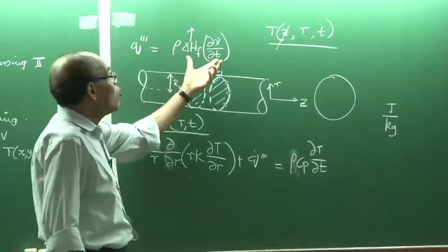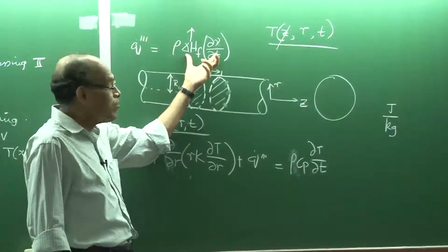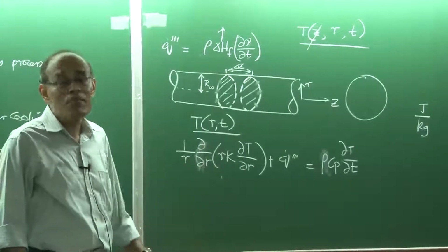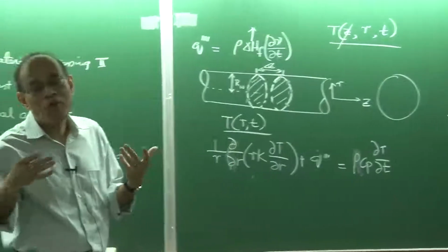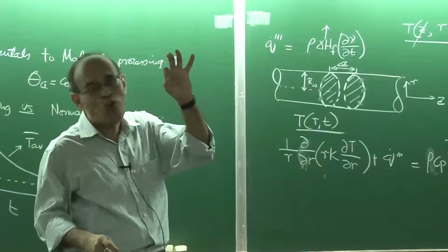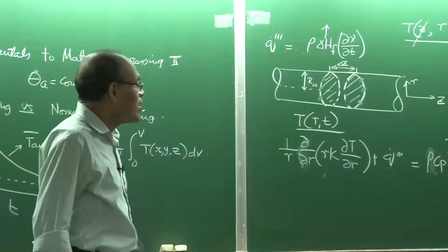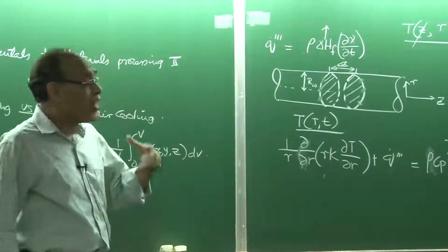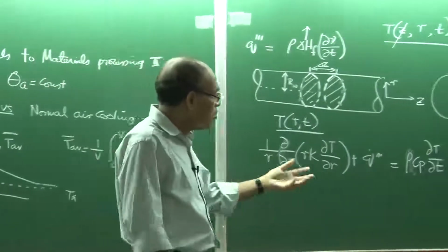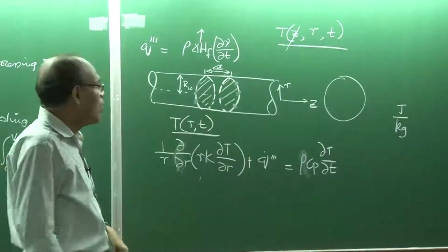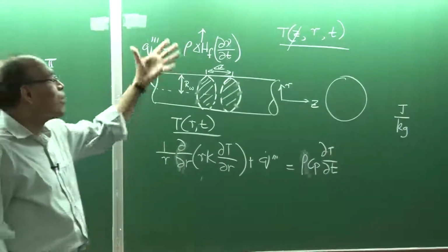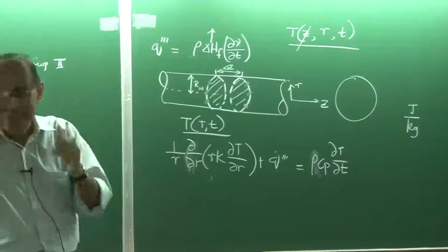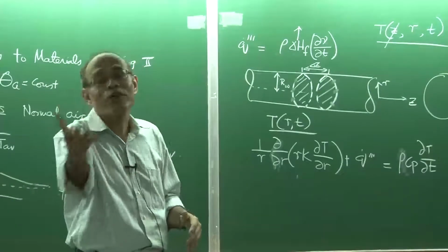Now the question is, how do you know how the phase change is taking place? For example, you can club with an iron carbon phase diagram, assuming that you are doing air cooling, and you know that the thickness is so small, nowhere will you get the critical cooling rate. So the time transformation diagram does not come into the picture. You can assume that the phase change is occurring close to equilibrium, and therefore you can apply the iron carbon phase diagram and the Lever rule, and find out at any point of time how much of austenite is being converted to how much of perlite.